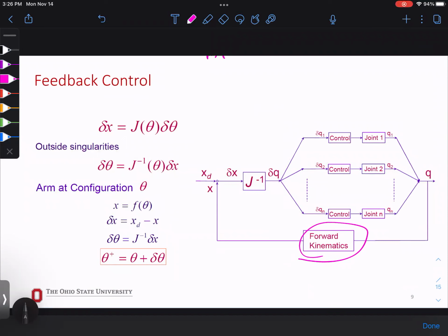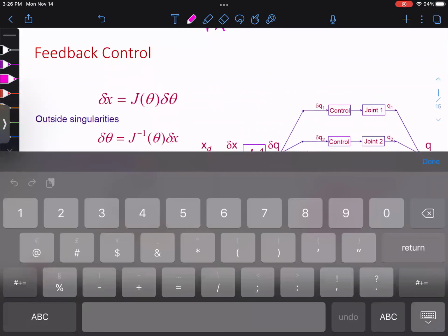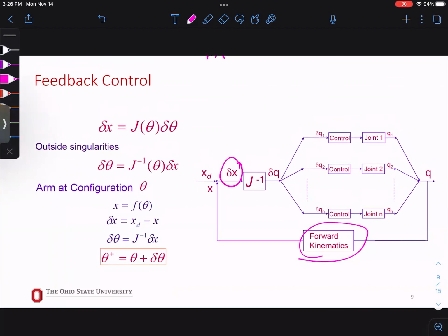So first, using the inverse kinematic, you can go from desired position to possibly the joint variables. Now, we will send the command to our actuator, and then so we are moving the system. We don't know if we got where we wanted. So we have to calculate the positions again and compare. Then if there was any difference in the position, we can apply our inverse kinematic again now for this little distance and shift everything, move everything a little bit and check.